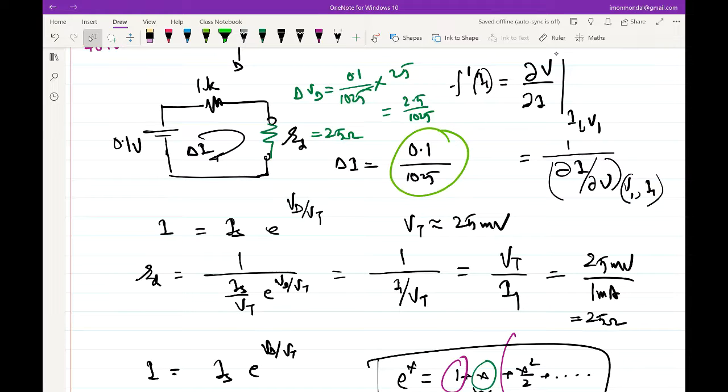Do I solve for each of these I1, delta I1? That becomes a problem. If you have different types of nonlinear elements, you have to ensure that the approximation is valid for all of them. So at the end, you have to go back and see whether the approximation is valid for each of them instead of doing it for the entire loop. But in principle, what you are saying is correct.